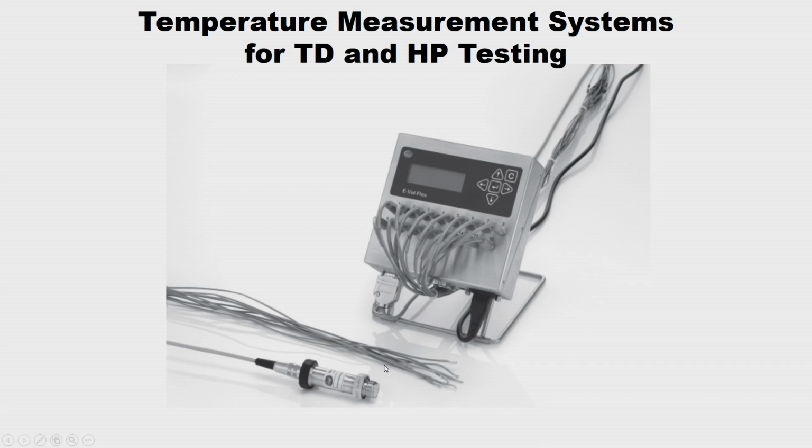Coming to temperature measurement systems, this is one example where thermocouples are connected to a data logger. This has 16 channels, so it can be kept in the process, the process container or the product, and the temperature is recorded from that. Nowadays the T type thermocouple is mostly used, and now we also have PT 100.